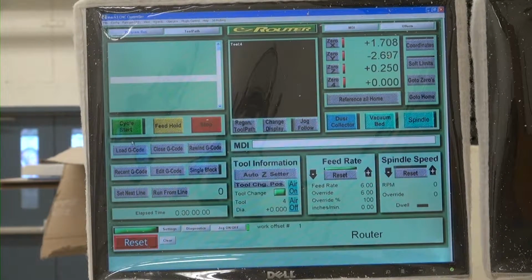But first, we're going to prepare the machine to run. In advance of milling, you want to warm up the bit, which just literally means you want to hit spindle. To turn the spindle on, you can hear it running, and slowly bring up the speed to about 10,000, using this up button. So it'll be warming up while we do the rest of this.